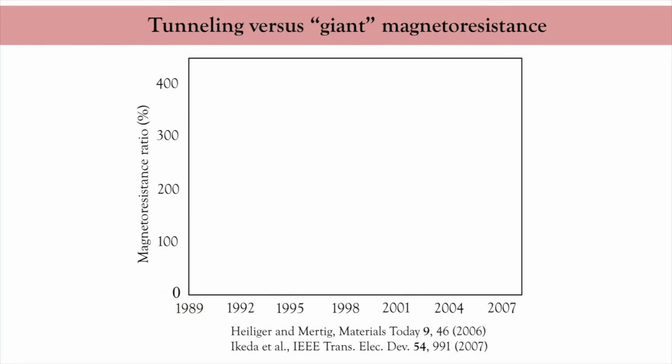Since the discovery of the giant magnetoresistance in 1988, immense progress has been achieved. In the decade that followed Fert's and Grünberg's experiment, it was quickly realized that metallic spin valves could never yield more than a few percent at room temperature. This is why the effort has been focused on magnetic tunnel junctions. As I mentioned previously, the superiority of tunnel junctions comes from the fact that the resistance of the tunnel barrier, which constitutes the active part of the device, dominates over the resistance of the metallic layers composing the stack. Therefore, you can put virtually as many additional layers as you want, the TMR remains dominated by the barrier.